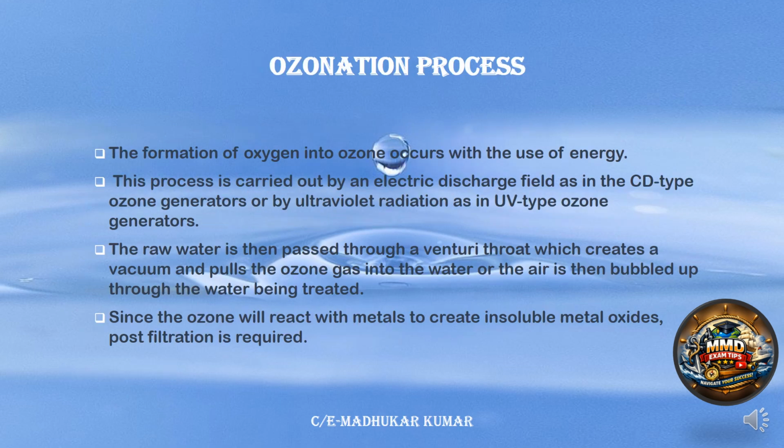Ozonization process. Ozone is O3, and it has good disinfecting properties. Onboard ship, you can see the ozone generators, and they are creating the ozone and sending it to the unit. The raw water is then passed through the venturi throat, which creates the vacuum and pulls the ozone gas into the water as the air is bubbled up through the water. And this is how it is being treated.